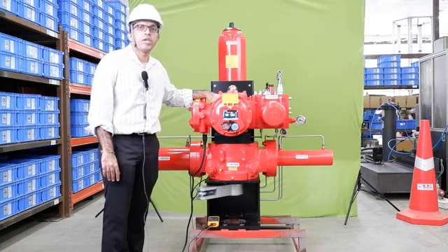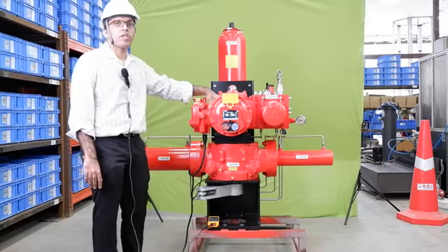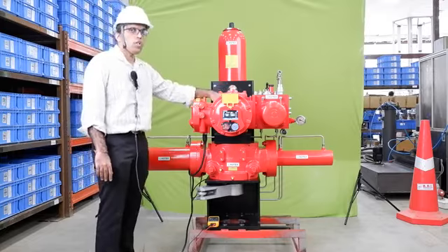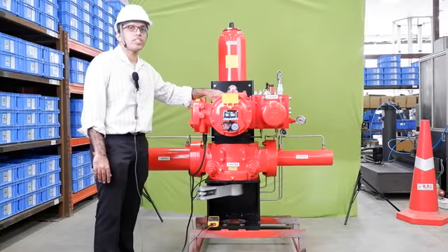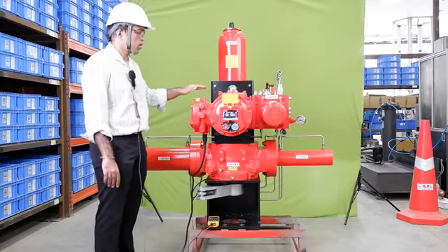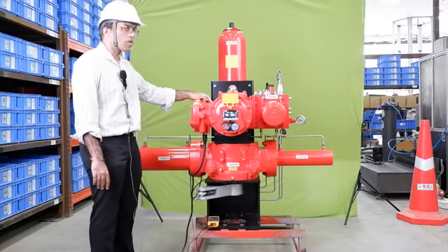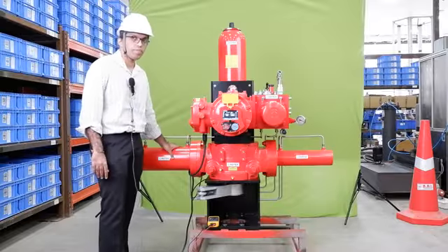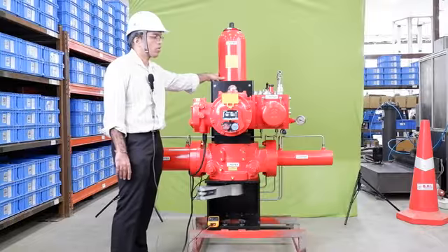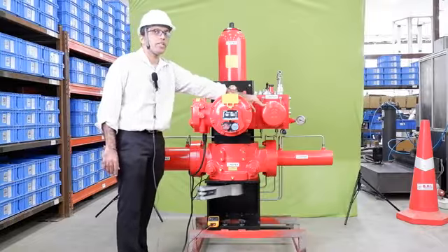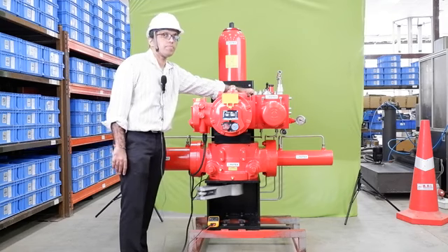Hello friends, we are demonstrating the modulating electrohydraulic actuator of Rotex. All the components in this actuator are self-contained in an EHD enclosure. The different components are the EHF head mounted on a double-acting Scotch yoke actuator. We have an accumulator for backup pressure. We have a motor to maintain the pressure, and we have an oil tank which acts as an oil reservoir.